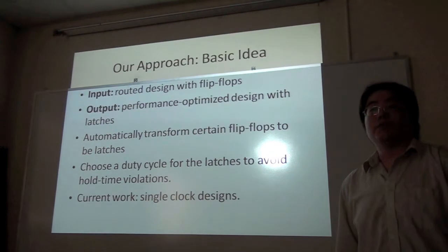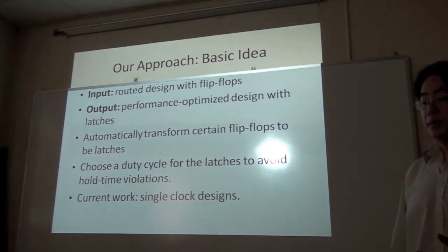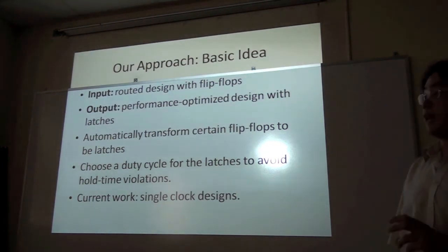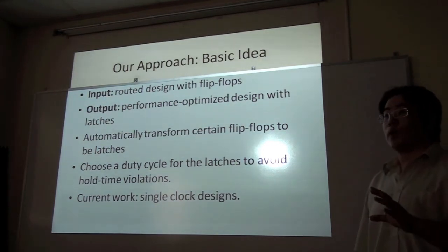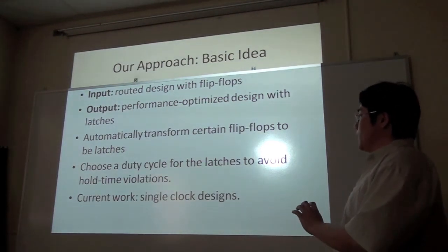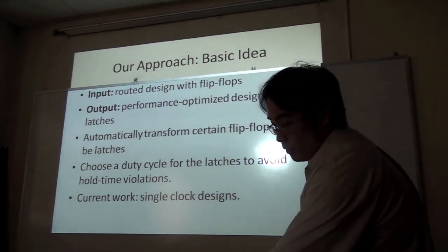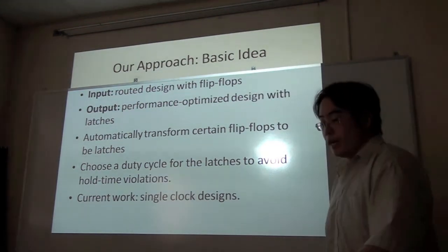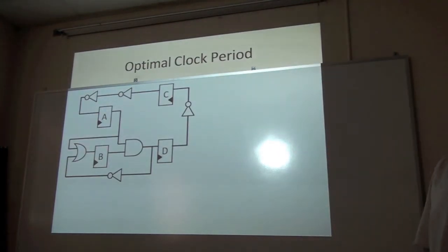The basic approach of what we tried is, given a routed design with only flip-flops, we would like to selectively replace some of the flip-flops with latches and choose a duty cycle for the design such that no hold time violations occur. Currently we're only working on single clock designs. There are a couple of stages to our approach. The first stage requires us to calculate the optimal clock period for a given circuit.